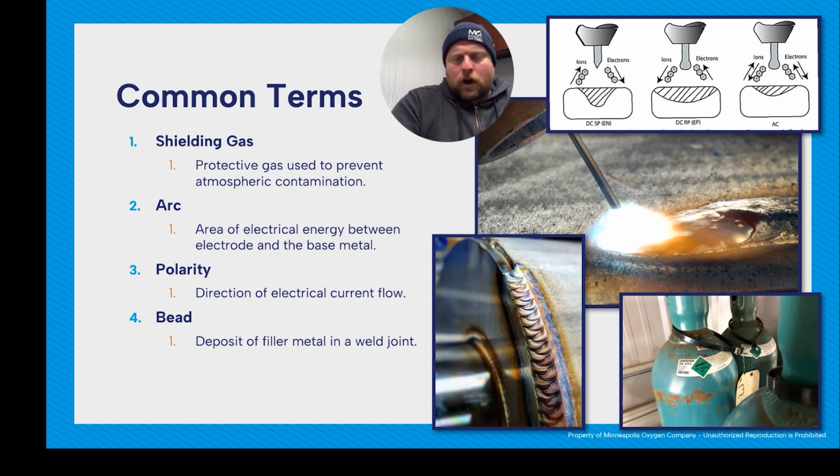So things like argon, CO2, nitrogen. If you're doing laser welding, you can have a little oxygen, depending on the type of mix, that helps with stainless steel, like a 98/2 MIG mix, things like that. So many different types. The main thing is the shielding gas is going to protect your weld from the outside atmosphere, so we're not getting a bunch of contamination or other gases into our molten weld metal. And it's also going to help shape your bead. In MIG, it allows for different transfer methods. Shielding gas does a ton for you.